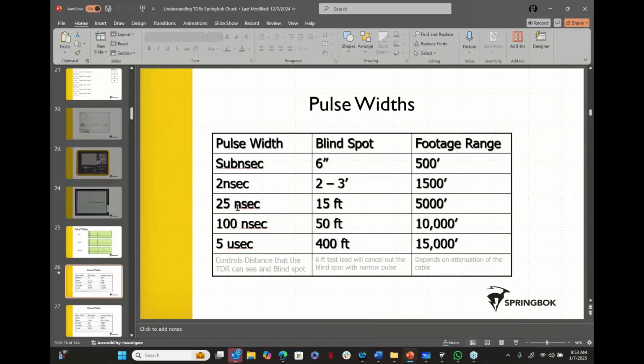Perhaps you were in a 50 or a 75 nanosecond pulse width, which had about a 20 or a 25-foot blind spot. So understand, the rope analogy, this wave going down the cable, it's not just at the very beginning, but it's going to be similar as it goes down the cable. This is almost quite literally a 25 or a 30-foot wave that's going down the cable, right?